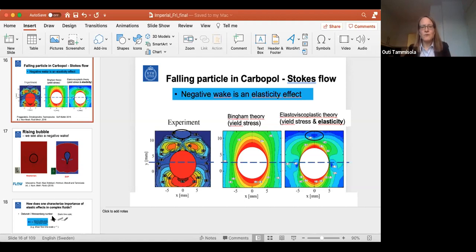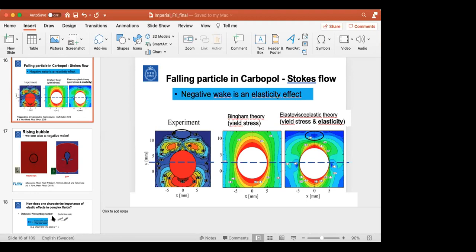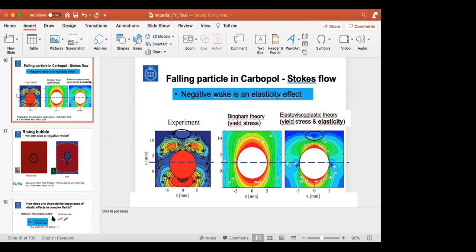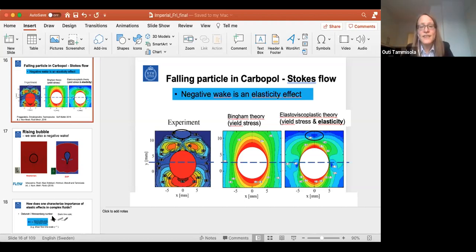It's different if we look at this. We have used the level set in other studies. In this case, you have the level set field, which doesn't distinguish between one bubble and the other, and then they can automatically merge and break up, but not with front tracking. So you come with some advantages. Sharp interface. Sorry? Your interface is sharp. Yeah, for front tracking, yes.